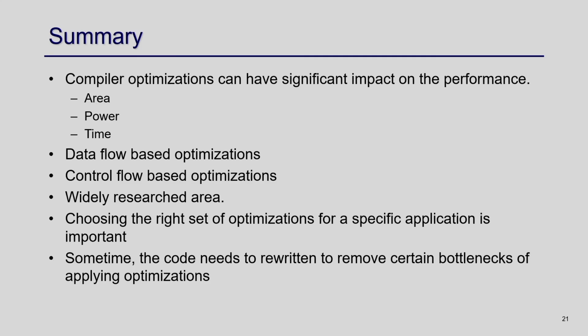And it is not a one-time process, it is an iterative process. When you try to develop highly efficient hardware, you have to do design space exploration, applying different combinations of the optimizations and seeing how they are impacted, and you have to understand the impact. Sometimes you might see that because of the initial code you are not getting the impact. So, you have to manually change the code a little bit so that certain optimizations are enabled, and as a result you get efficient hardware.